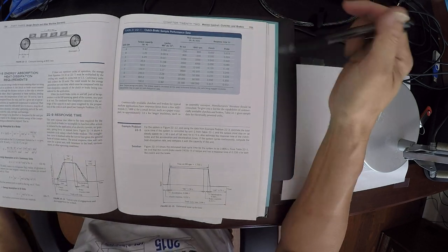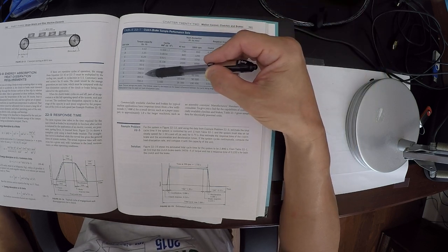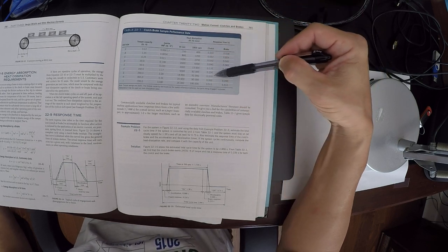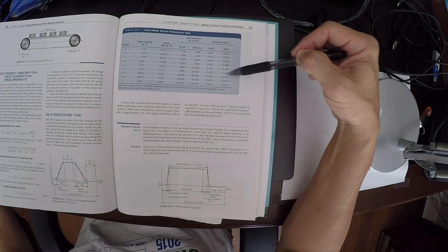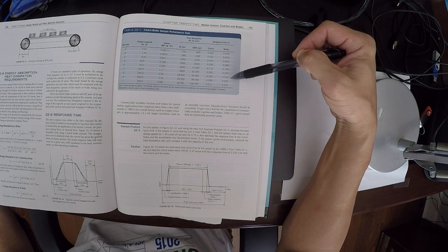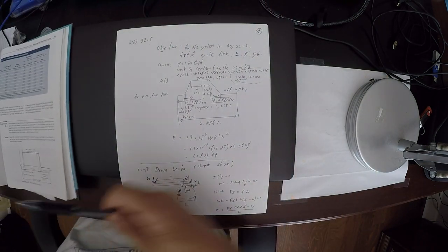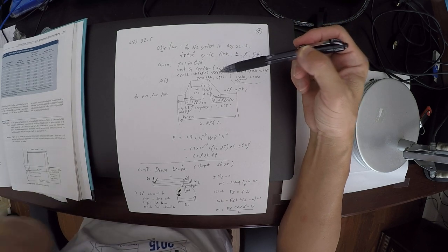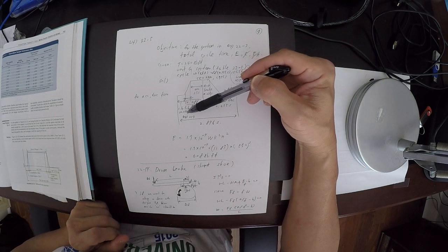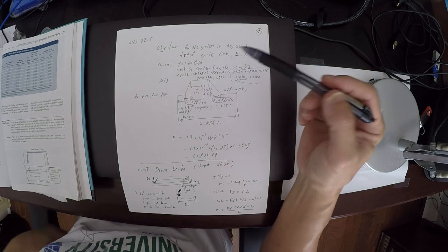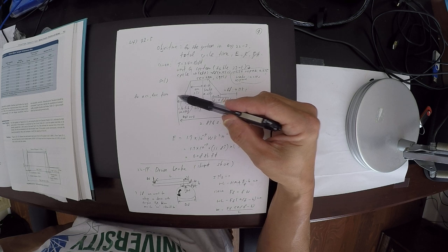So you can figure out these response times quick. So basically, for a given 240, the response time here for the clutch is 0.235, same as the brake, 0.235 second. So with this response time, you can actually start with the clutch. This is a clutch. Response time. This is basically the time that you apply the clutch.